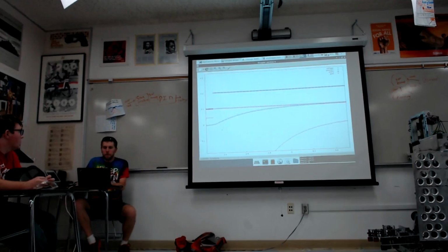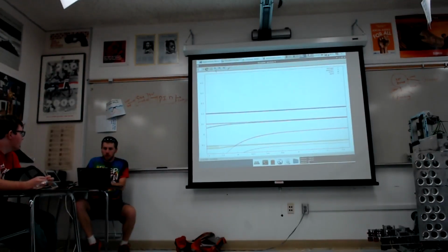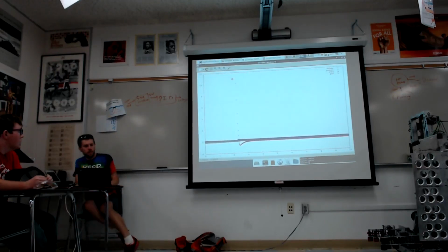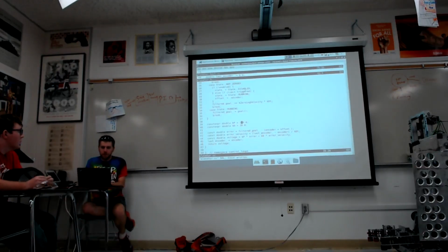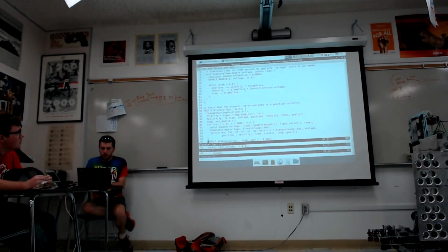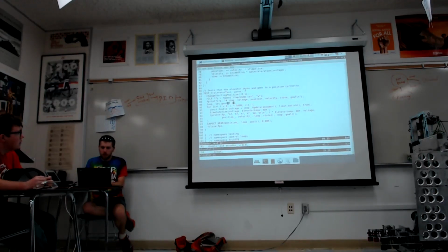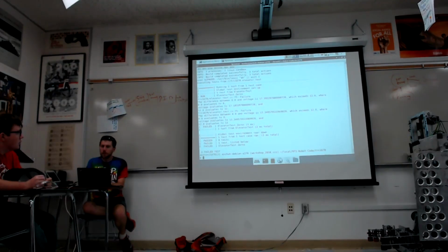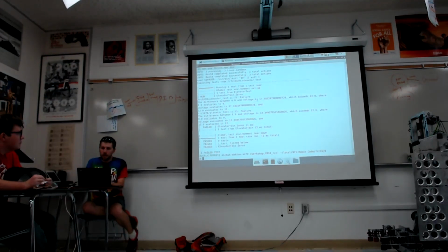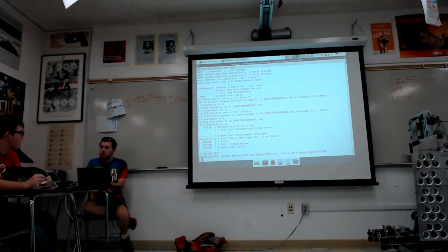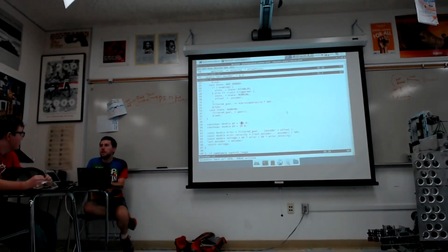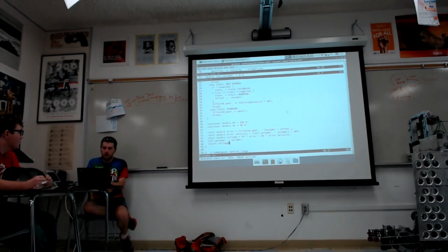Okay. Currently, we're not having a voltage below 0. Yeah, so let's break it. So what if we try and go further? Just fails. So we asked for 17 volts and then 13 volts. So we should probably fix that. Simple fix would be just max your voltage at 12.